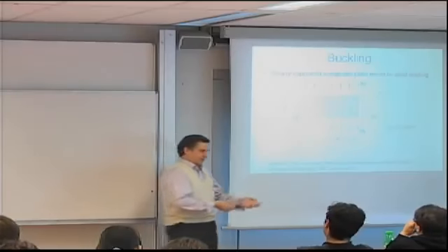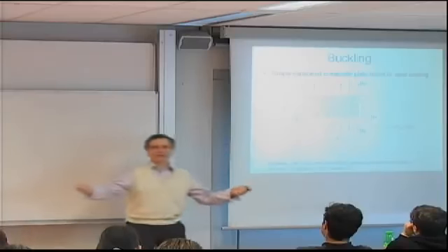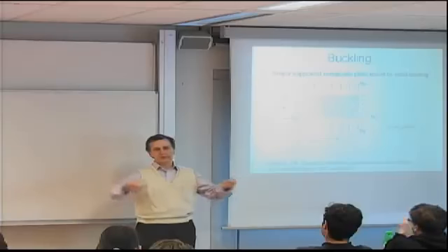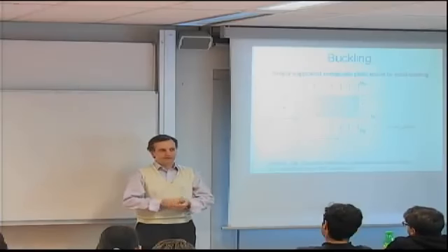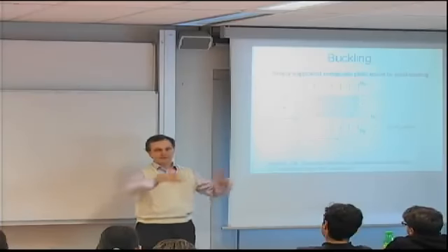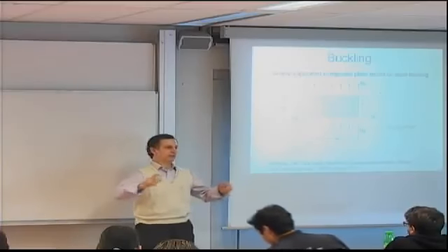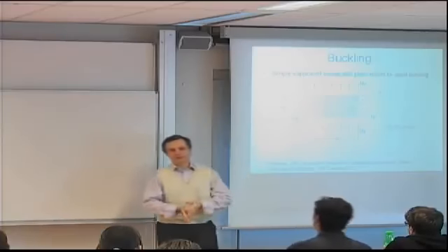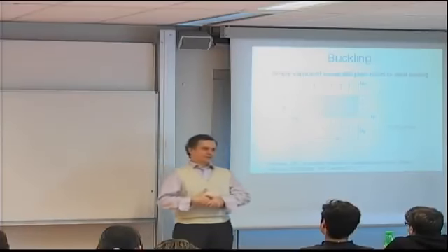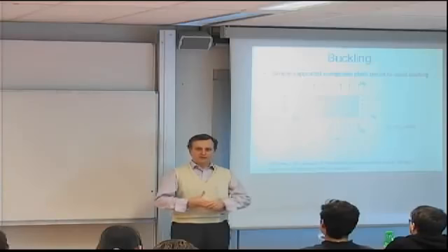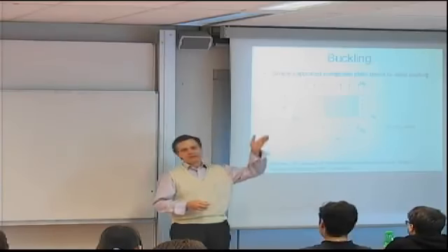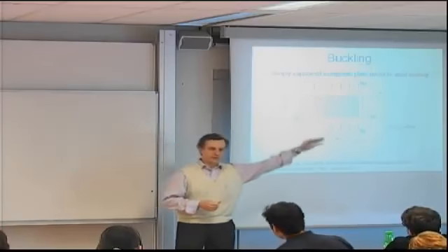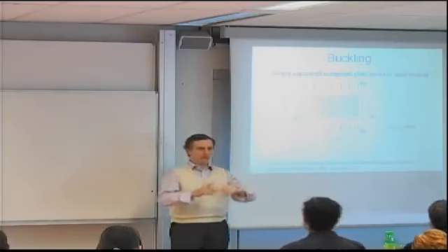So if the B matrix is not 0 and I start loading, what happens in addition to compression? Yeah, there will be bending, torsion, all kinds of things, which means now the idea of out-of-plane deflections happening suddenly is not there anymore. So you may have heard the word bifurcation. Bifurcation means that there's a path which is like a straight line. All of a sudden, although it changes completely, it reaches like some kind of a crossroads.